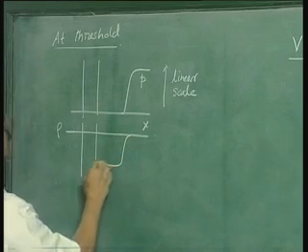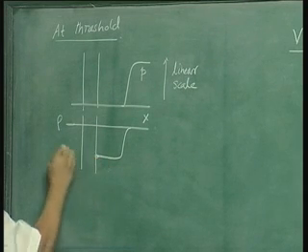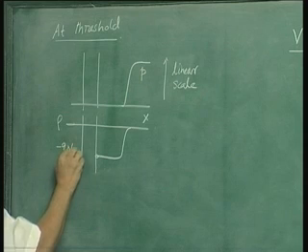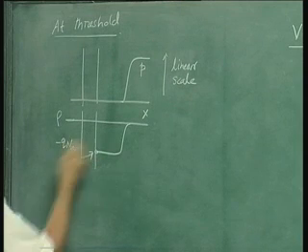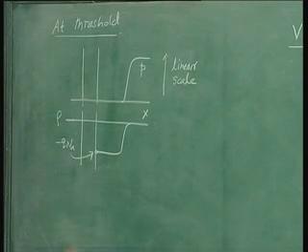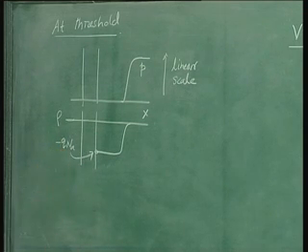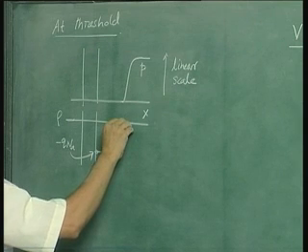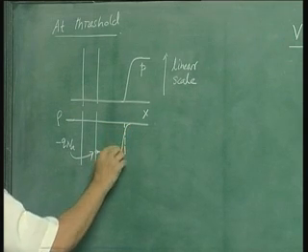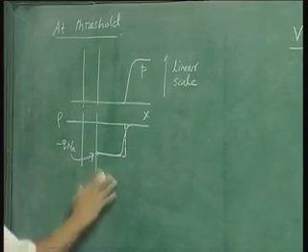So that is the space charge, where this value here is minus q times Na. Approximately, we know from our p-n junction theory that in the depletion layer the space charge concentration is minus q times the ionized impurity concentration. We are assuming complete ionization. Now we will assume the depletion approximation, that is, we will assume that this region has an abrupt ending for simplicity of analysis.